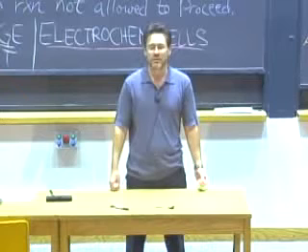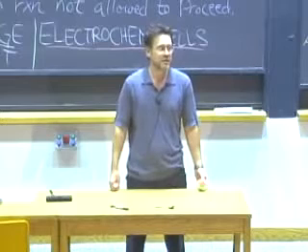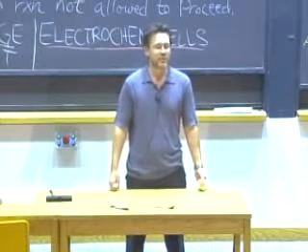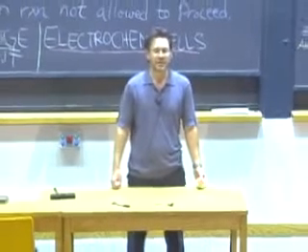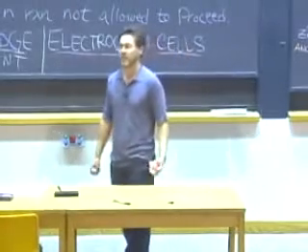You probably know that zinc anodes are usually present in several places on boats so that electrolysis doesn't occur and corrode away the metal parts of your boat. And instead, the zinc sacrificial anode is oxidized away and is a source of electrons. So that's an important principle.